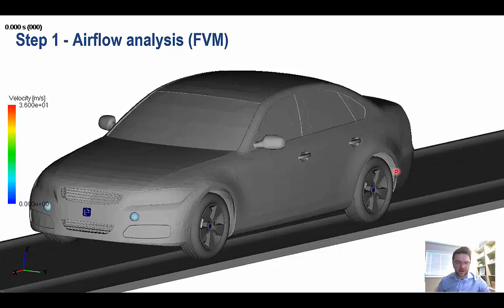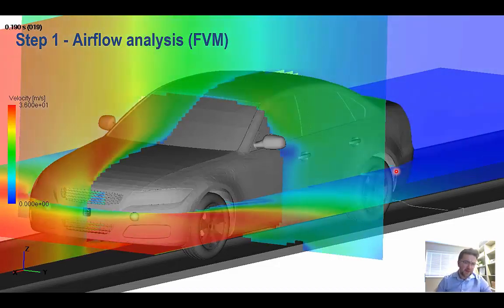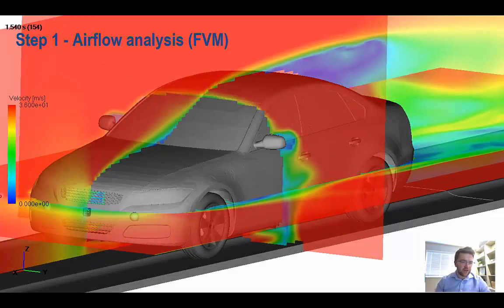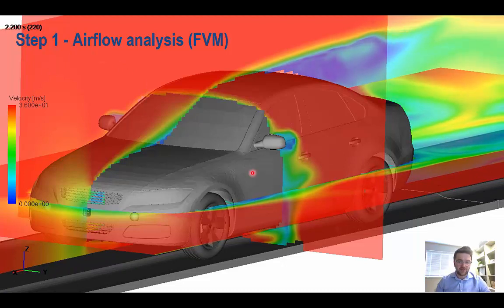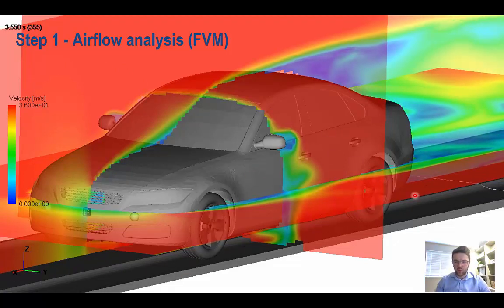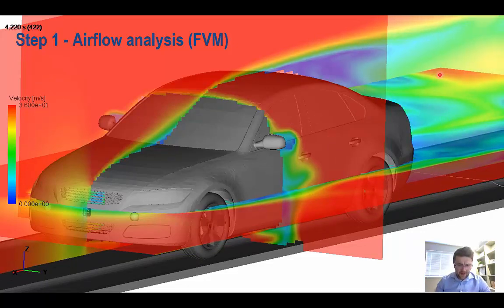Now you might be thinking ParticleWorks is a particle-based solver, not a mesh-based solver. Well, ParticleWorks thankfully has an FVM solver built in specifically for the purpose of calculating airflows, either around an object such as a vehicle or within something like potentially a gearbox or an e-motor. As we already mentioned, what we're going to be doing is injecting air on the left-hand side here into the path of the vehicle and then seeing how it develops around the back of the car. And we can see this wake forming here, for example.